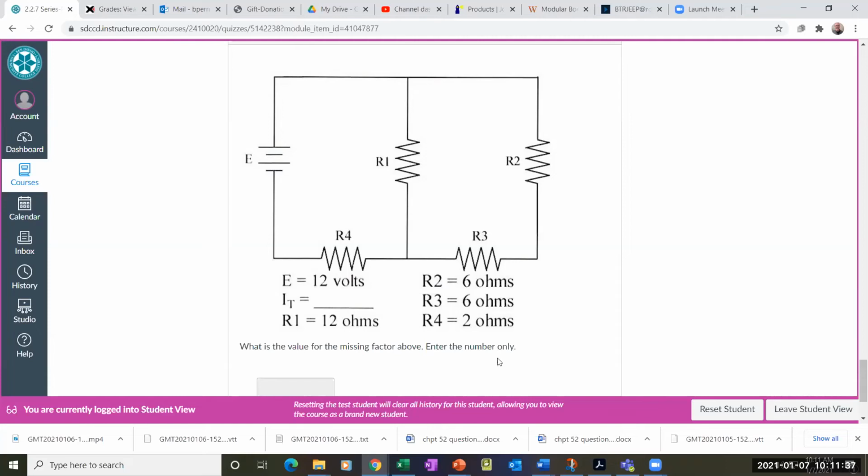And then the current is 2. Right. Well, hold on. Don't forget about R4 here. Wait, everybody's talking all at one time. My effective resistance, you're correct, is 6 ohms for my loop plus 2 ohms for R4 for a total of 8 ohms. So if I take 12 volts and divide it by 8 ohms, what's my current flow?